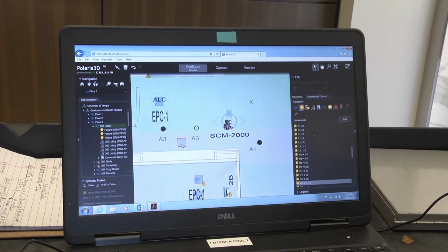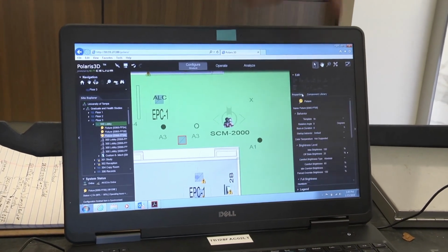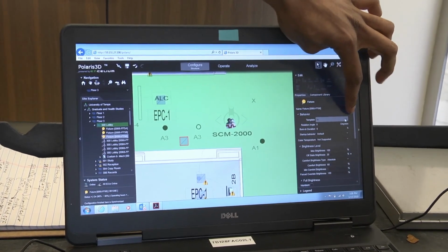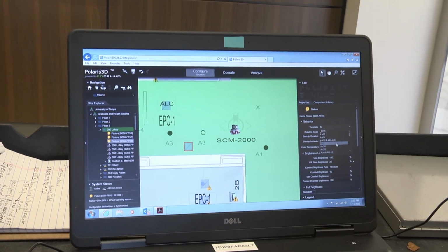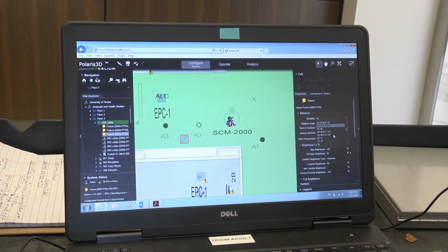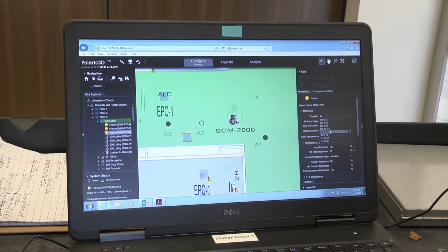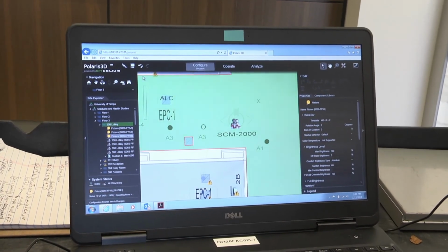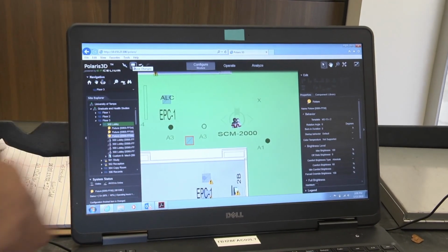Select that device. Now go to properties. This one up top here. And then where it says template, you had fixed, drop down, and look for the one you just created. Is it M? Right there. I'm still selected. Now it swapped it. It doesn't look different because it's the same dimension. So if it had been a different dimension, you'd have seen it changed.